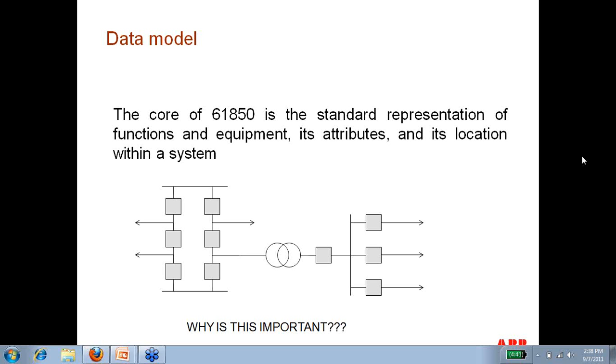And what it is, is an implementation guideline for 61850-9-2, which specifies the sampling rate for protection functions, the sampling rate for monitoring functions, the configuration of voltages and currents per data stream, the accuracies of time synchronization requirements, and so on. So it is not a new standard per se. It is based on the released and published 61850-9-2, but it's an implementation guideline that fills some of the ambiguities that were left open with the release of the current standard. So that's what it is.